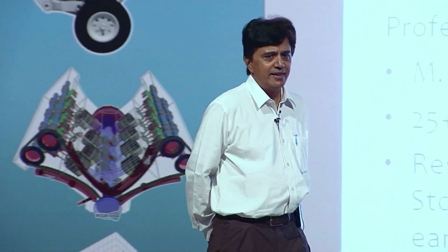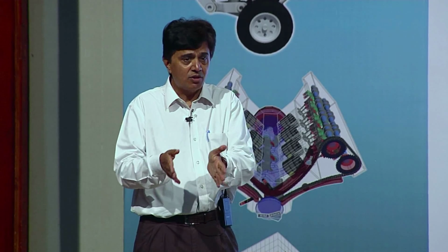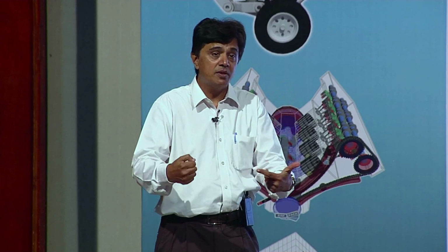Oh no, these are very difficult questions, but I would also contest whether you can really evaluate stiffness correctly, simply because of boundary conditions and other things. Even natural frequencies are not found correctly. I showed you some experimental simulations where natural frequencies are also not found out correctly, leave alone damping. Damping shows high variability. So my approach would be, you respect that there is variability and get an answer in probabilistic terms. Then you know this much confidence you can have in your answer. But if you say damping is 0.1%, and you don't have any confidence band on that, that's a very poor answer. The Bayesian method tells you it is not 0.1, but its distribution is this. So you make whatever engineering decision, that is more information.